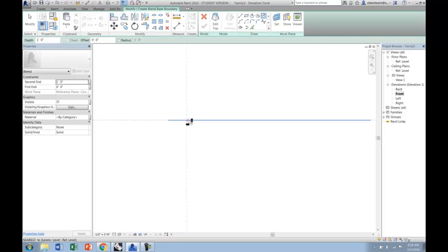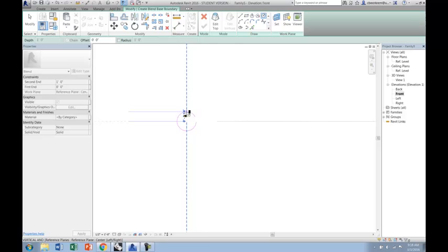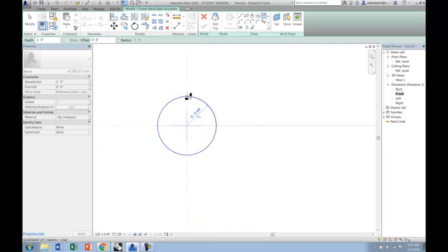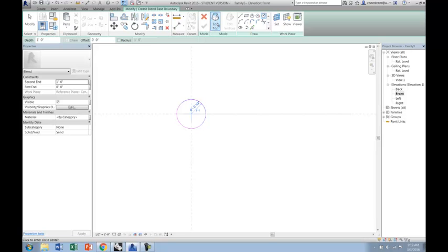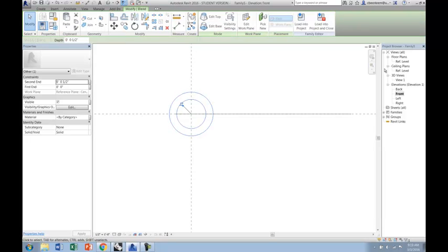So I'm going to just draw a circle and snap it to the center. Let's make it say 1/2 inch on the inside, and then we'll hit edit top, and again come out and maybe go 3/4 inch on the other one. You can see the first and second end over here are defined with a certain depth. So I'm going to go ahead and select that and change it to 1/2 inch deep, and then hit the checkbox. And let's take a look at this in plane.